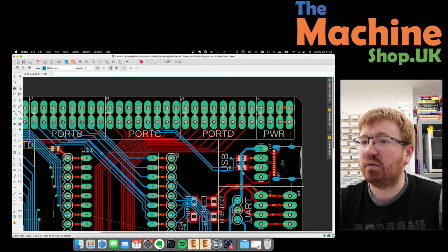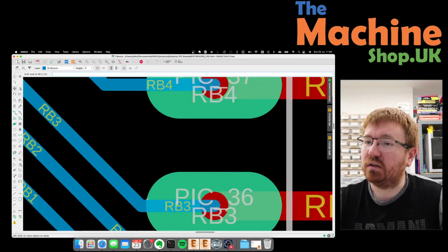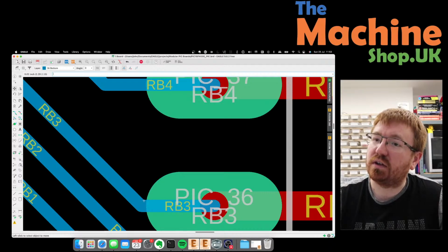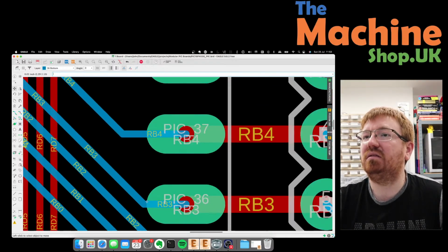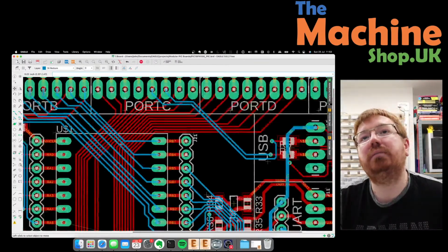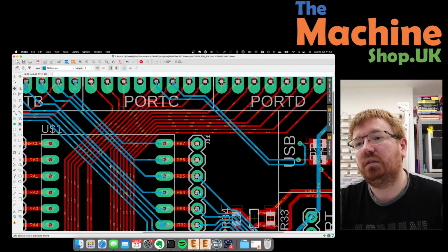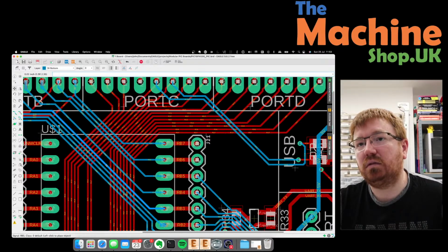Can I get that to the point where it's a... That's okay. What I don't want is anything less than 90 degrees on these bits. 90 degrees is fine, unless it wasn't, but it just means that there's no pinch point. Don't like the pinch point. It doesn't make it easier for manufacturing, and it also can cause signal issues. Okay, let's get them looking nice and neat. There we go.